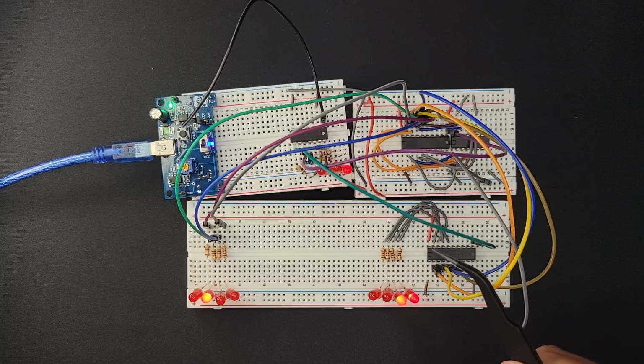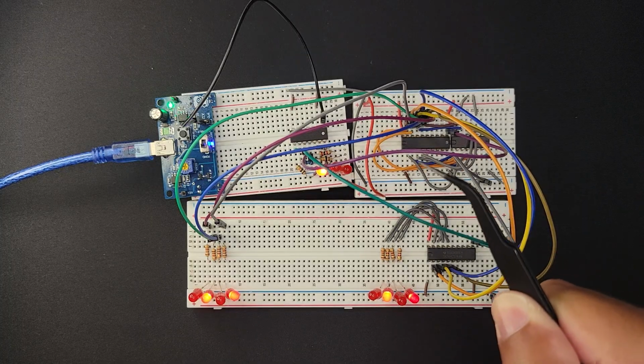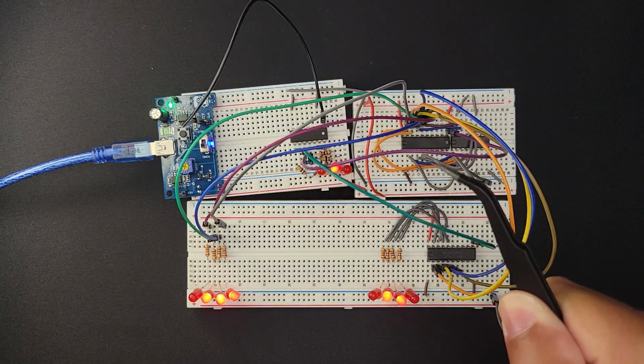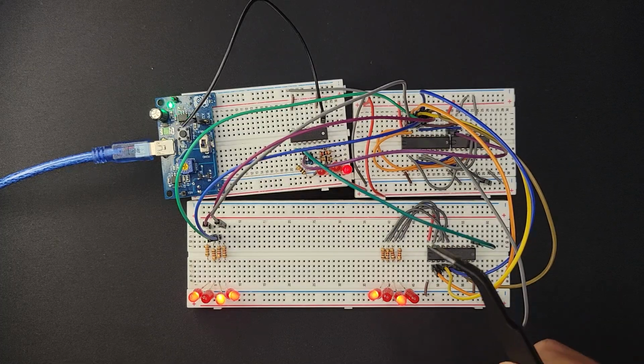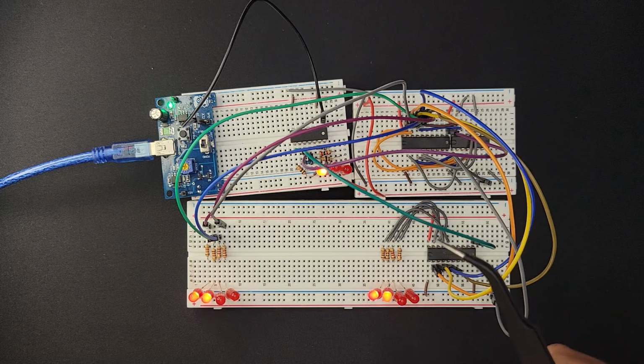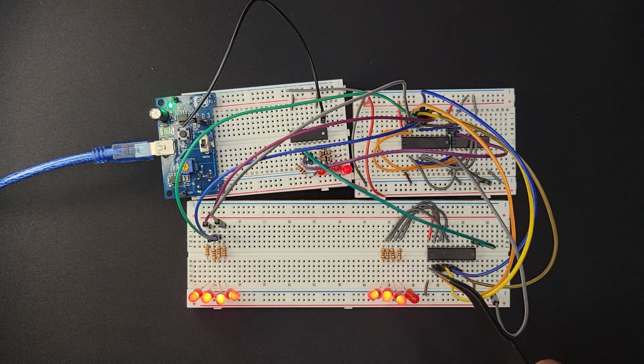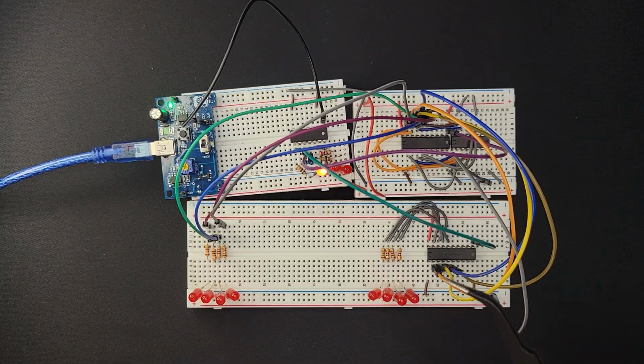So the memory address register grabs that 0, then he goes up in the decode. But by the time decode is happening, the memory address register would have already had the correct address and done its job. And then when the next cycle comes now, instruction pointer has already incremented on the previous cycle, so memory address can get 1, and then it repeats. So instruction pointer is 1 ahead after handing it off to the memory address controller.